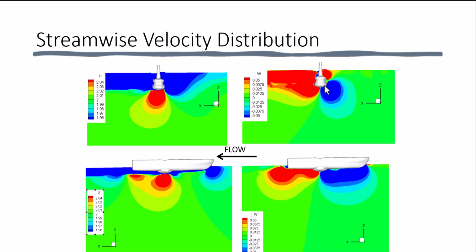Thus, any of the beams pointing forward see a downward velocity, and the beams in the rear pointing rearward see an upward velocity. This combination violates our homogeneity assumption made for the equations to transform beam velocities into horizontal components and leads to a low bias in the measured velocities within the disturbed region.